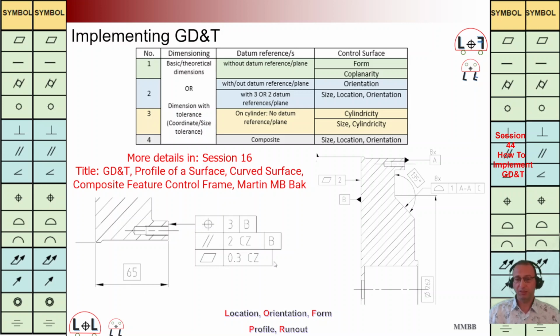Back to B, because as we have talked about, A is dependent on B, and B is qualified by this flatness. The TZ for that is 2. It is not in contact with anything. That's why we are going to consider 1 or 2 for that.